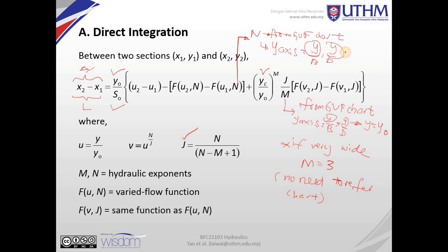Both y here, we should use y equal to yc, the critical depth. So if very wide channel, we need to use n equal to 10 over 3.